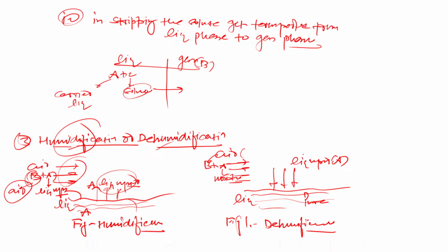So here you can see the liquid vapor or water vapor has been condensed out from the gas into the liquid. That's called dehumidification: removal of water vapor from air by condensation on a cold surface, and condensation of organic vapor such as carbon tetrachloride out of a stream of nitrogen are examples of dehumidification.